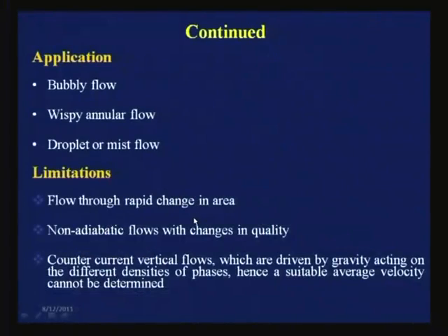So, whenever we encounter any situation where there is flow through a short nozzle or an orifice, with rapid acceleration and rapid change in area, since the equilibrium condition is not valid, we do not have the homogeneous flow theory. So, certain specific cases I would like to read out: flashing of steam water mixture through short nozzles and orifices. We cannot use the homogeneous flow theory.